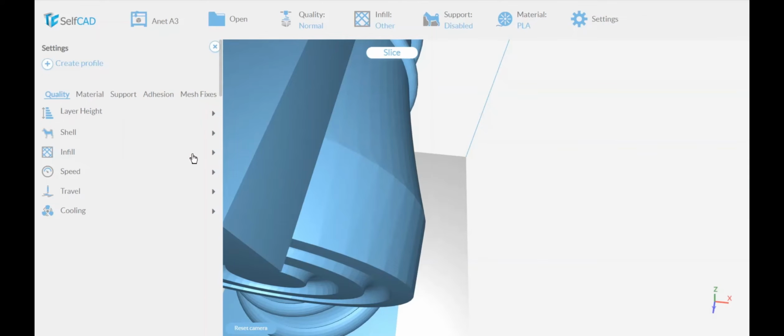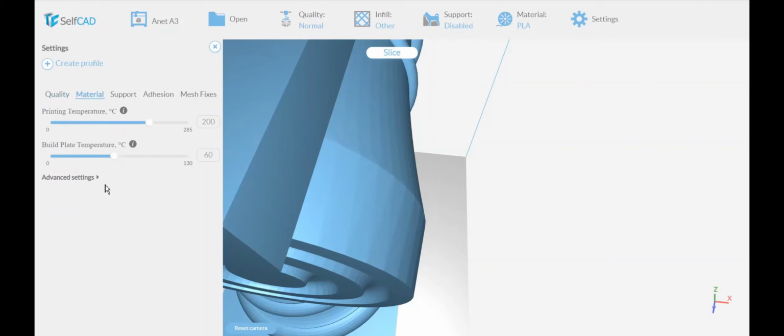And then let's say you have a particular printer, but you have 5 different types of objects. Each one needs different settings. It's just too tedious and too complex to set them every time. So you can basically create a few profiles for different types of objects, and then every time you have a similar object, you select from one of your profiles. Definitely the more advanced you get into printing, you will need to create profiles. So different use cases, but it's not hundreds, it may be a few selected, so you can just create a few profiles.